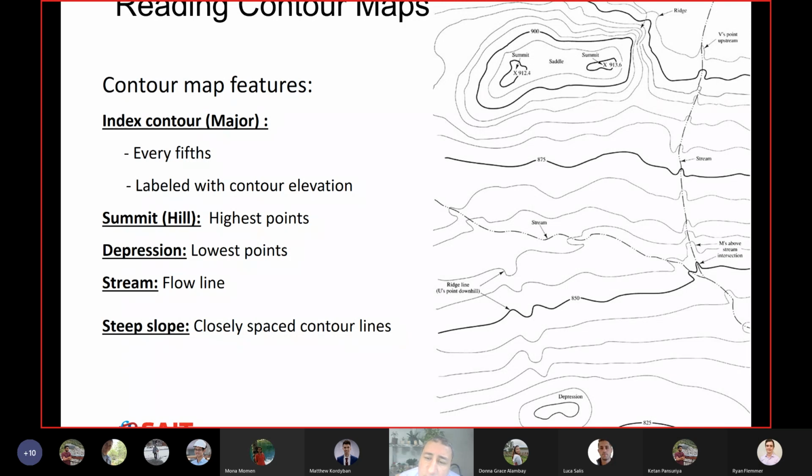Redundant, huh? It's extra. Yes. It's more than what you need. And that's why people a long time ago agreed that you don't have to label all the contour lines. You have to pick some of them and label them. And so that's why you will see here there is something called index contour, and there is something called measure contour. Those are the only ones that we label.